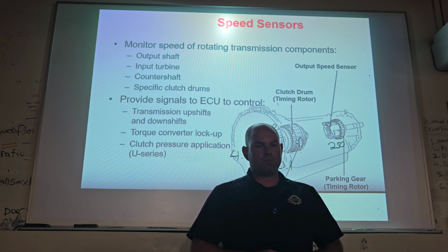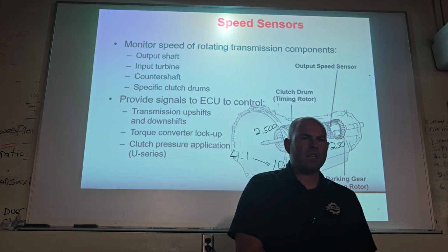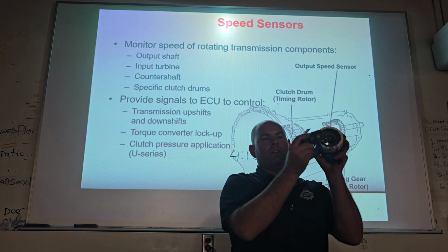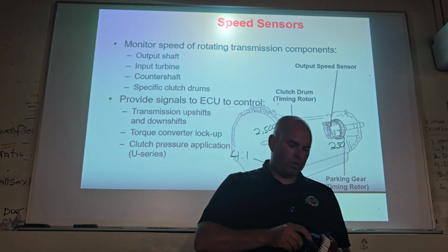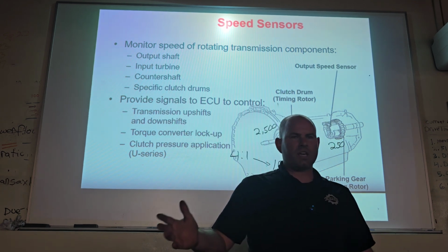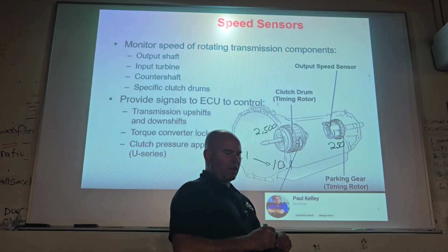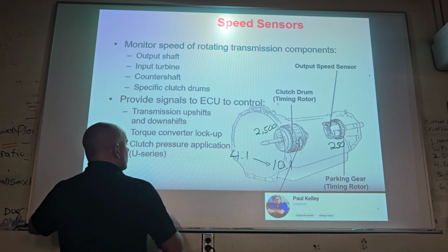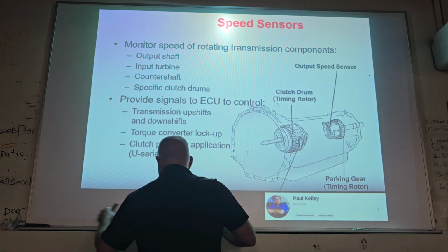Cool? You like it? Is it because someone put the wrong pinions in there? The first gear pinions are incorrect in here? No. It's because one of the holding components, such as C1, or B, I think it was B1. I meant to say B1 that was holding the carrier. That would be slipping. Cool? Very good on the input-output shaft speed. You need to be.